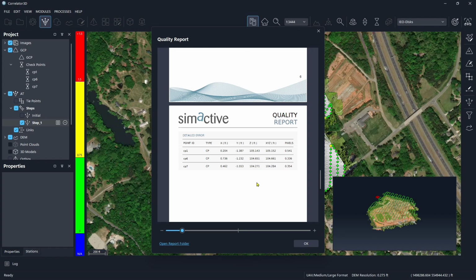One thing you could do is you could go back and you could reprocess your positioning information and maybe to the ephemeris, and then you could get the geoid offset for that area, and you could apply that geoid offset again, like I said, in the beginning of the processing. That's one way to solve the problem.